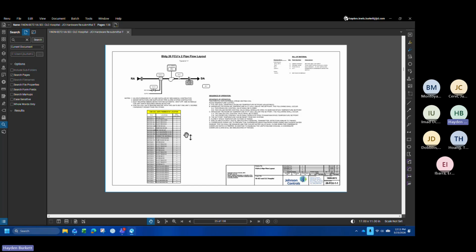When we go over our second training, I'll go more in depth on this, but there are alarm extensions built into Metasys, which have temperature ranges. I don't know what they are off the top of my head. But each air handler requires a specific supply air temperature. It's a range. They all have different supply air temperature requirements. It's something like between 51 degree discharge and like 54 degree discharge.